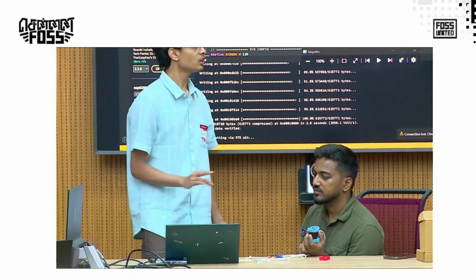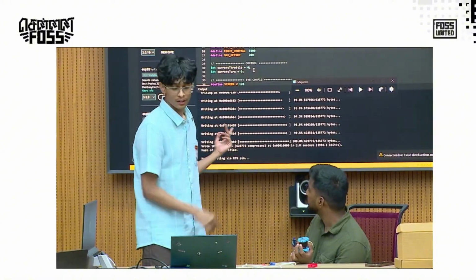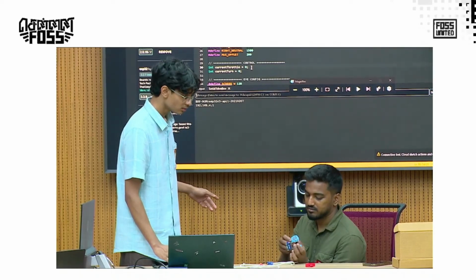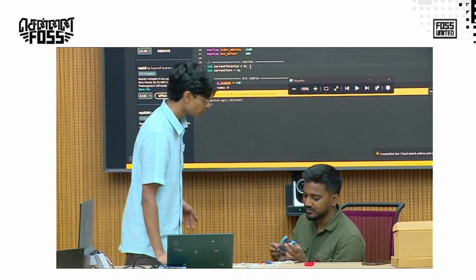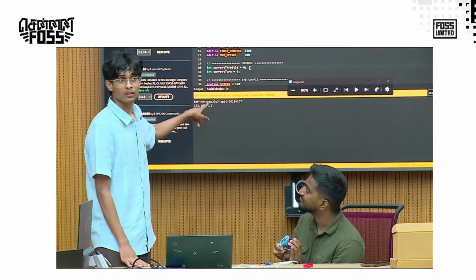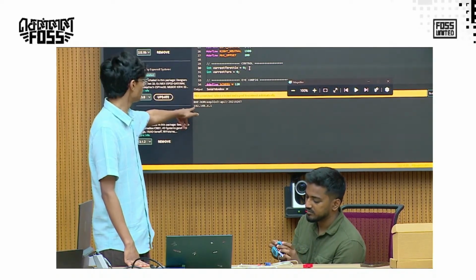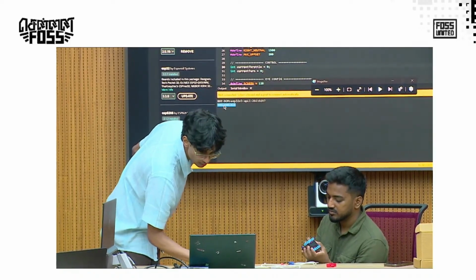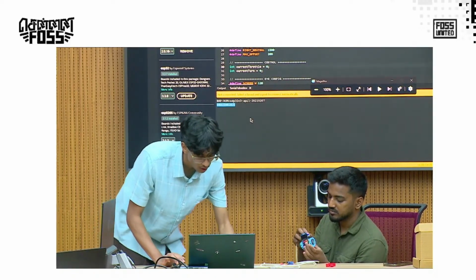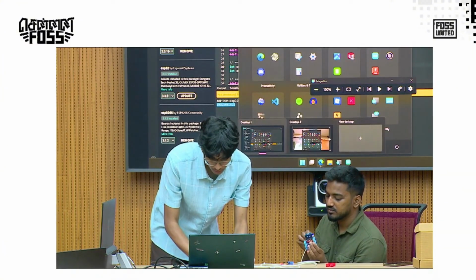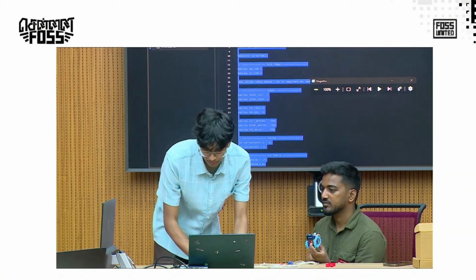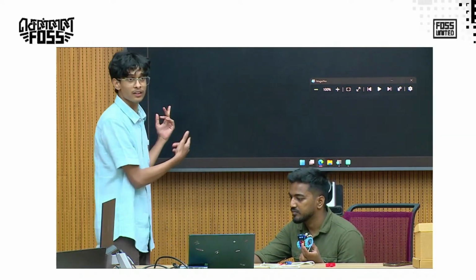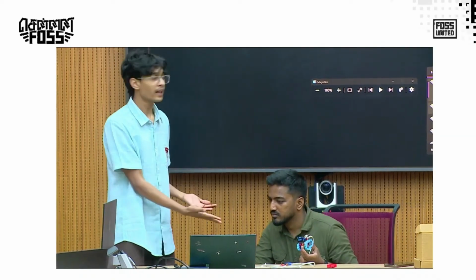So after this, on your Arduino IDE, you should press Control Shift plus M. That should open the serial monitor. Here you will get an IP address. What you have to do is copy and paste this onto your browser. After you enter the IP address, you should get a web UI to control the tank.